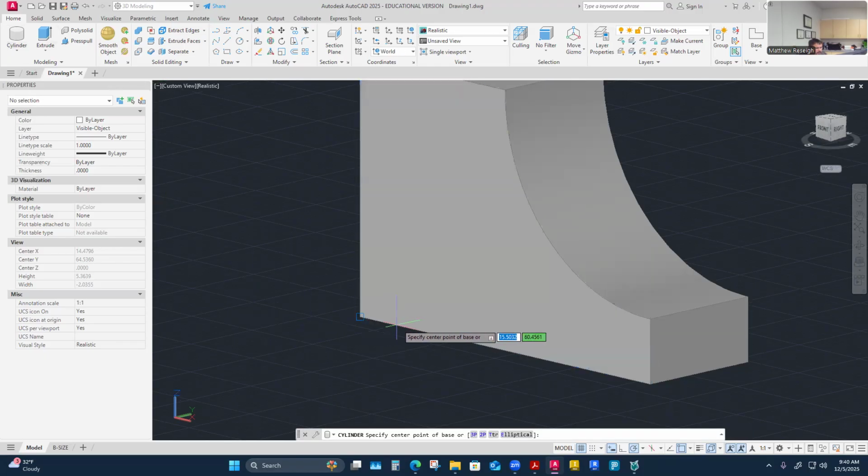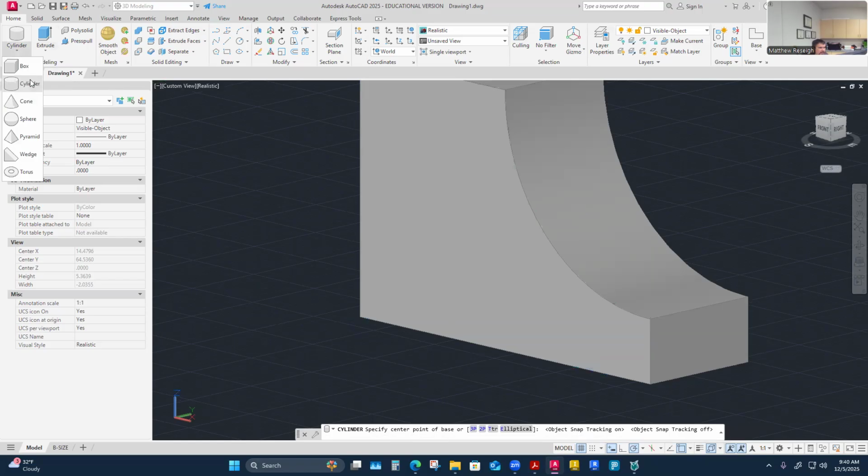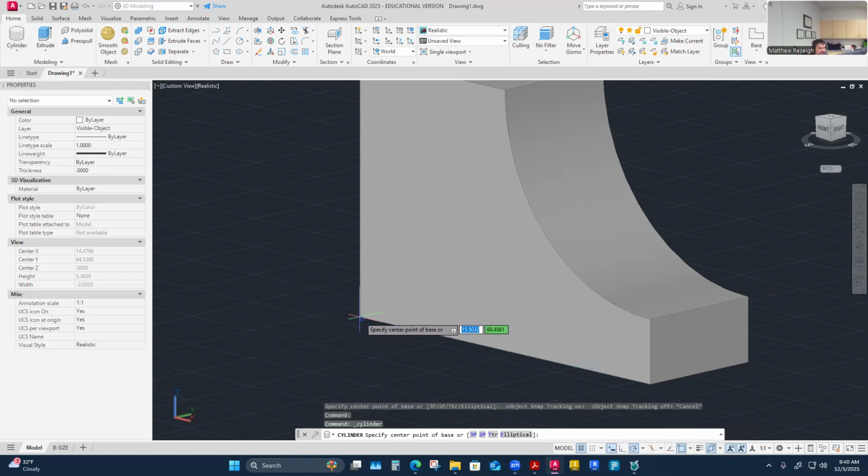Okay. Yeah, I think it might be this one, the object snap tracking, the little angular looking one. If that's not on, I feel like I can't hover, or I can't cursor over. I can definitely lock in on the point and then drag away, but it won't let me. Yeah, I think you're right. It won't recognize that I'm following a point here. So if this one's not on, I feel like that might be your trouble. Object snap tracking.